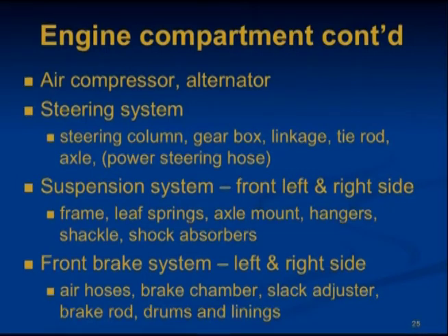For the front suspension, sight check the frame and the leaf springs, make sure that they're not shifted, cracked, or broken. Check that the spring hangers and shackles are secure. Make sure that the axle mounts are not broken or loose. The shock absorbers should not be broken or leaking and should be secure at both ends. The front brakes. Sight check the chambers for damage.